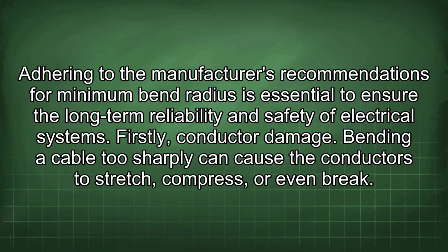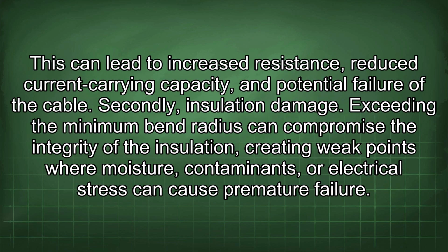Firstly, conductor damage. Bending a cable too sharply can cause the conductors to stretch, compress, or even break. This can lead to increased resistance, reduced current carrying capacity, and potential failure of the cable. Secondly, insulation damage. Exceeding the minimum bend radius can compromise the integrity of the insulation, creating weak points where moisture, contaminants, or electrical stress can cause premature failure.